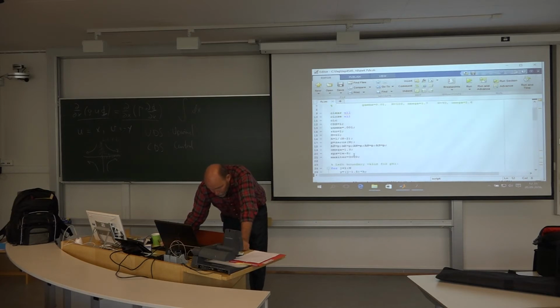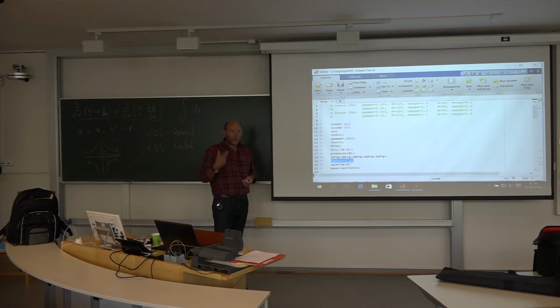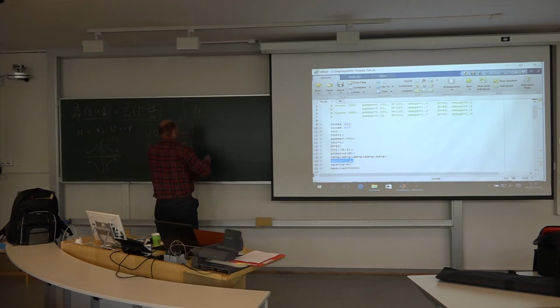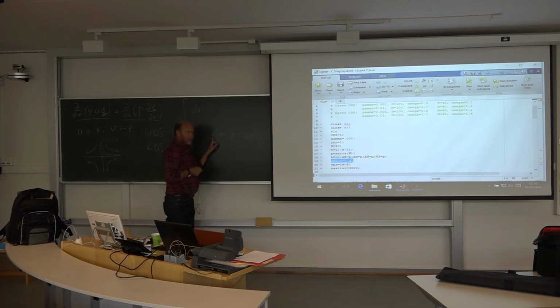So the stability analysis here is not that easy to do. So what I have to do now to make a solution is to use this over-relaxation factor as an under-relaxation factor. Remember what it does. You have your unknown, and then you calculate an adjustment of this unknown to find a more suitable value.